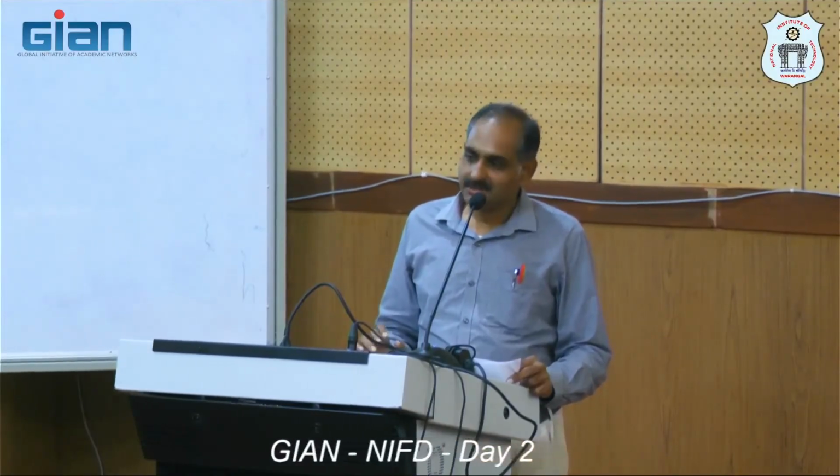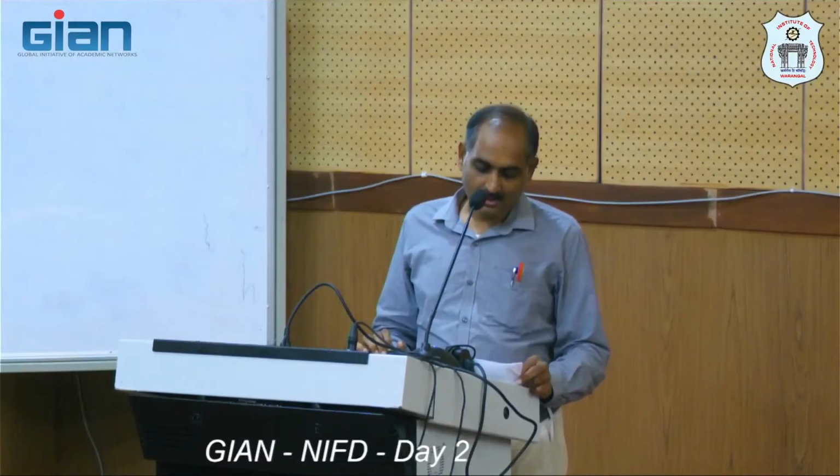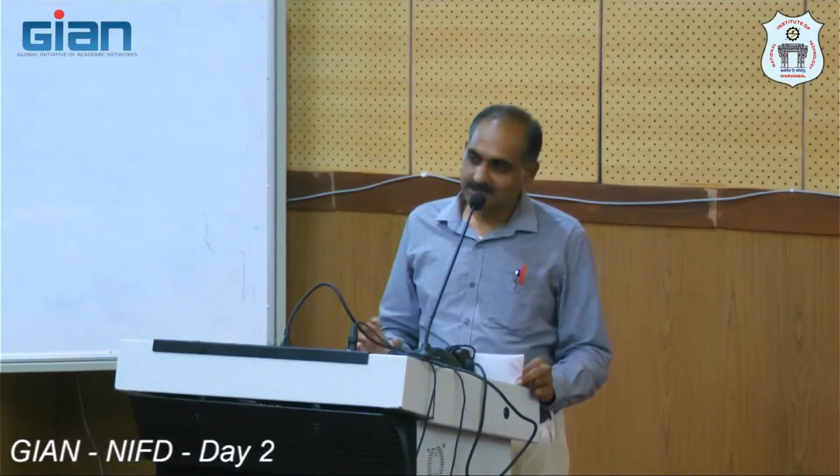So you know the main key categories of failure of electrical motors: bearing failures, stator winding failures, broken rotor cores or end rings in case of induction machines, high air gap eccentricity and unbalanced magnetic pull. So this may lead to the consequential rotor or stator problems.